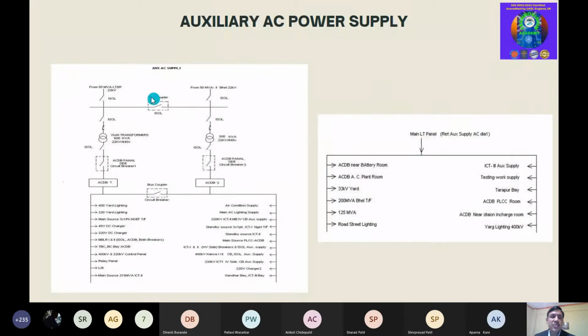Generally there are some transformers like 50 MVA transformers whose primary may be 220 kV, 100 kV or 132 kV. Even the tertiary of the ICTs, the interconnecting transformers of 400/220/33 kV, can be used: that 33 kV tertiary can supply the auxiliary power to your substation. So that also you can do.